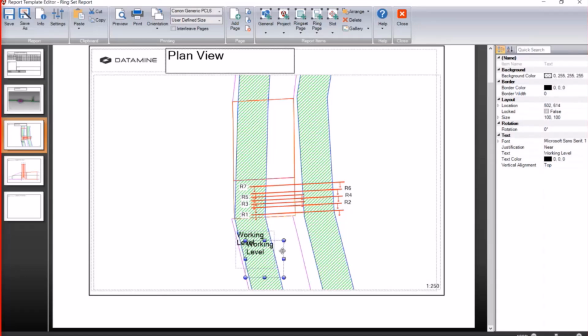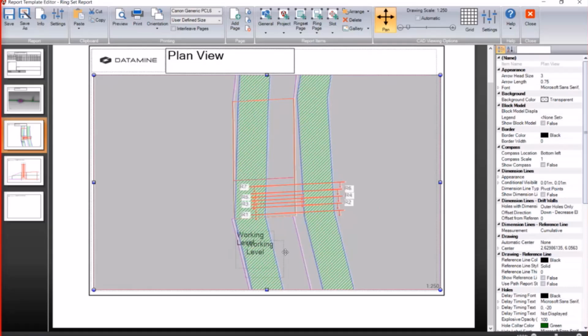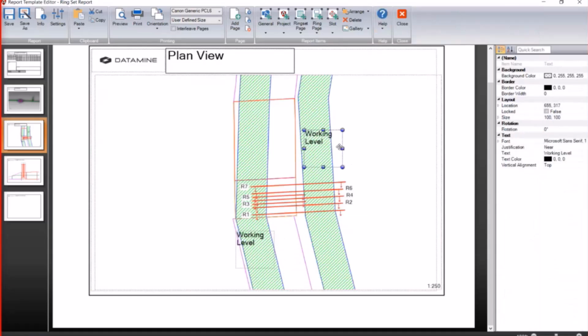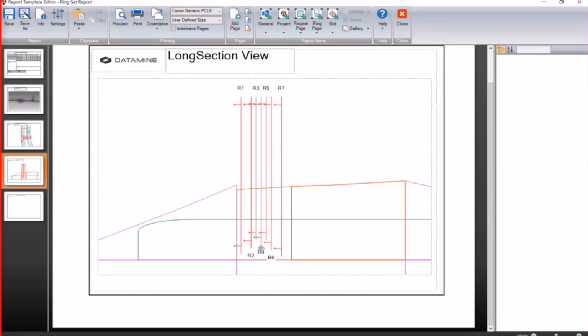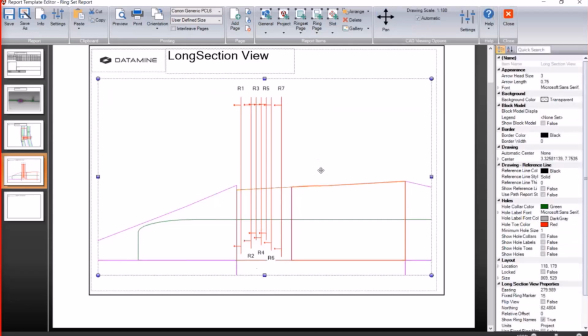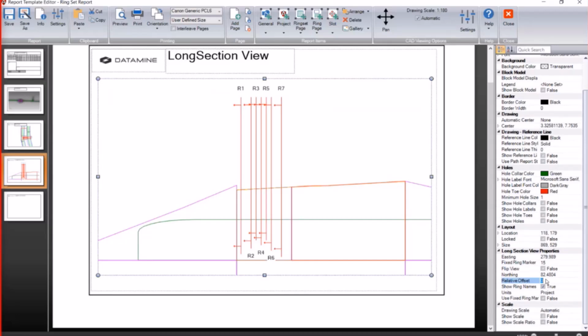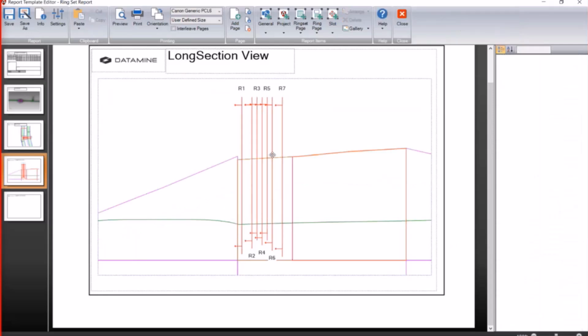And then I can also put same thing for this one as well, but because the shape is quite slanted, it's just showing me an exact vertical cross section. I can also change the relative offset. This is from the center line. Say I want 2 meters from that, so that will show a bit more. And then I can also change that scale.